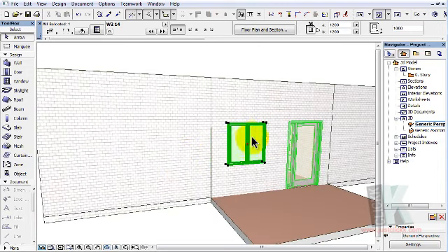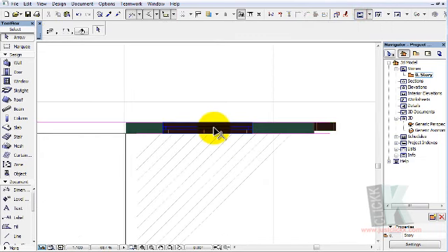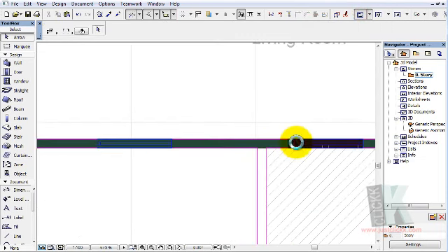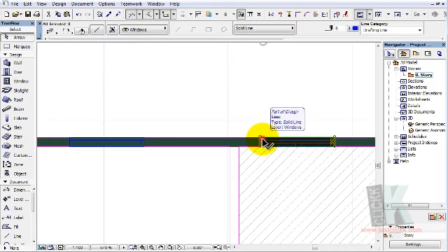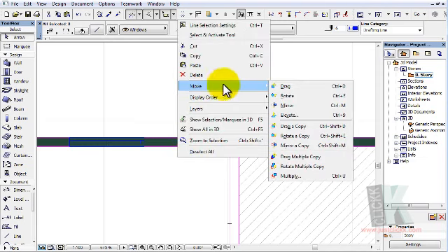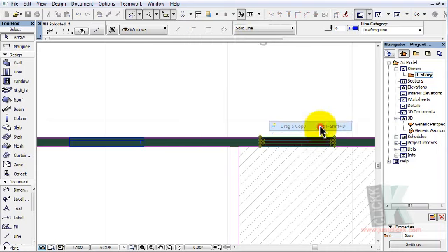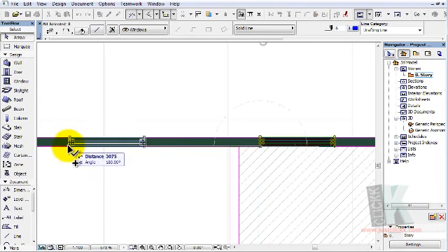So we can actually duplicate this window to place on the remaining places, or we can redo same using these techniques. So let's go ahead and duplicate this window. We can just copy this window to the next place here. How do you do that? You drag and copy. Now that I've selected it, I will just right click anywhere and say drag a copy, which is Ctrl Shift D. So I'll select that, and then I'll pick at a point at an angle, just click from there and then drag it to the position I want it to be.